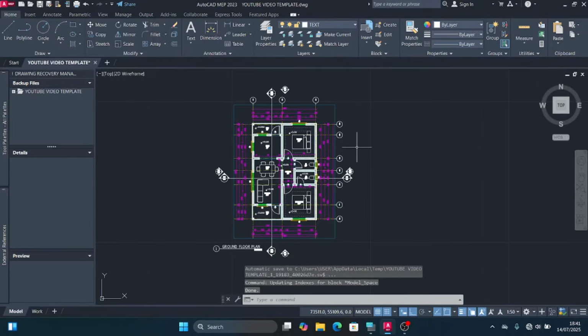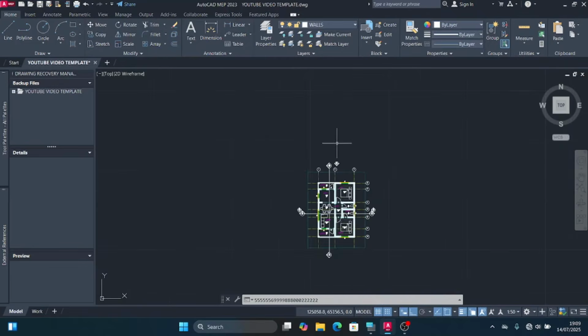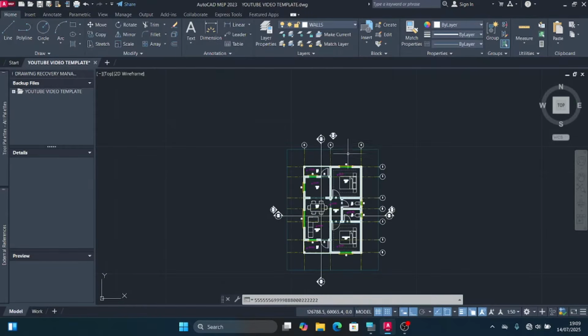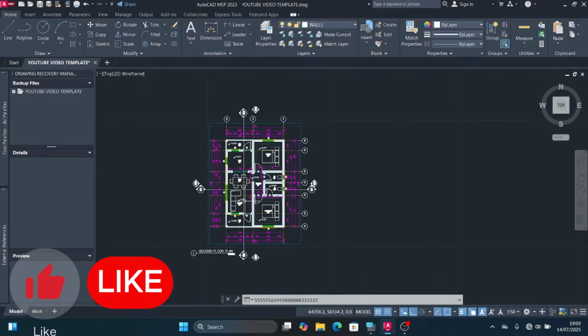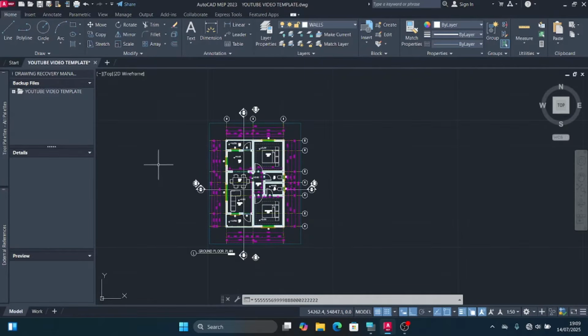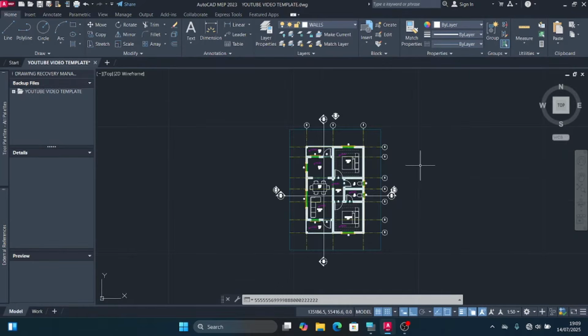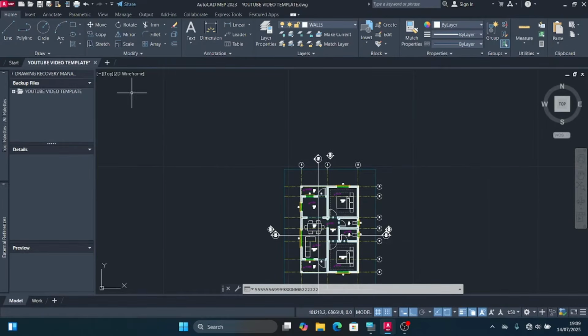I'll show you exactly how you can proceed with drawing the cross section. So I'll start with this reference drawing, and it's what we are going to use to generate all our cross sections, then also all our elevations. I simply got it from our floor plan right here. I just removed the dimensions and remained with this. So let's proceed with first clicking at the line command. Then I'll draw a horizontal line just above this reference drawing.